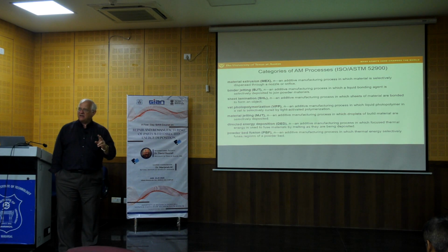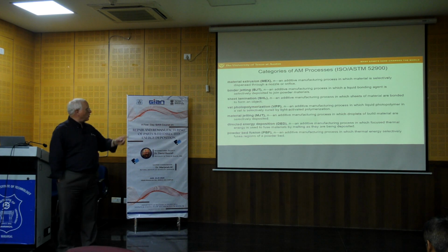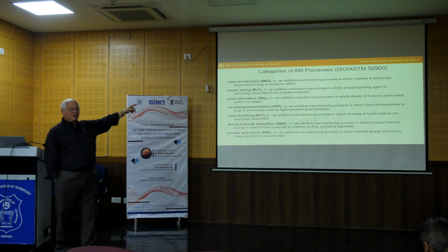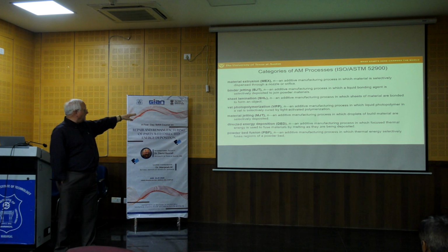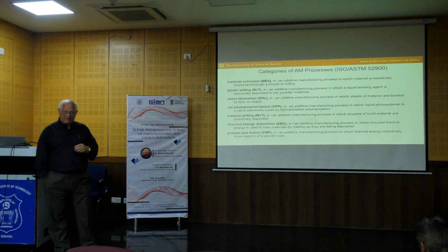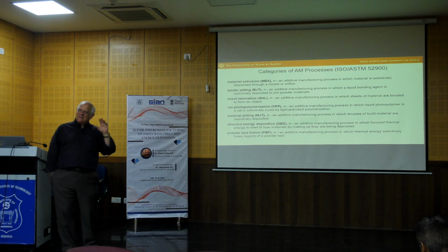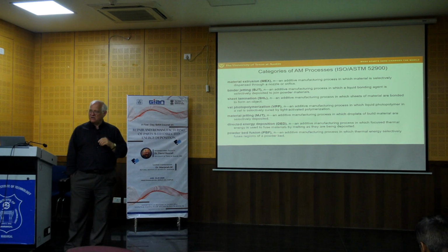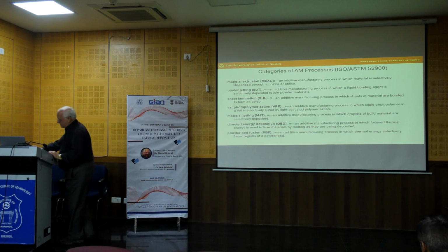The other way is the binding mechanism. So are we using extrusion? Are we using a binder? Are we using photopolymerization? Are we using directed energy or a fusion approach with the powder bed? So the binding mechanism and the feedstock are typically the distinguishing features of this.